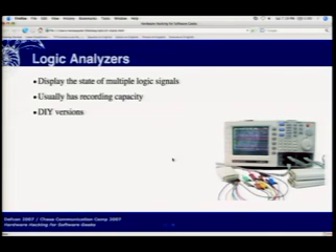They'll also be called generically 2-wire buses for I2C or 3-wire buses for SPI, even though SPI buses are usually 4 wires because they have a clock wire, a data in, a data out, and then a slave select to select which device on the bus is being talked to. When you're using a logic analyzer, you can look at all 4 of those lines and see how the chips on the board are communicating, and whether that's where the bugs are in your code or your layout or whatever.